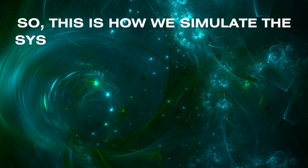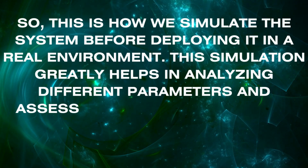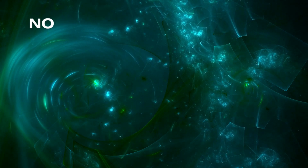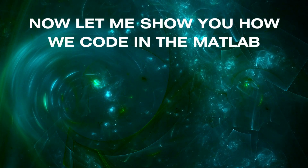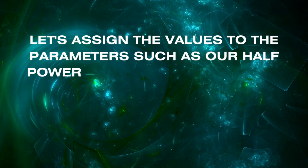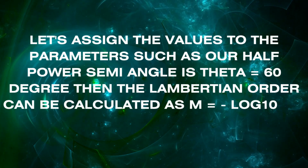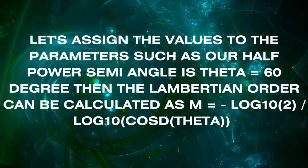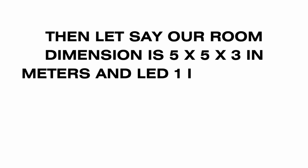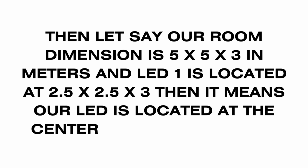So this is how we simulate the system before deploying it in a real environment. This simulation greatly helps in analyzing different parameters and assessing the performance of the system before it is actually installed in the room. Now let me show you how we code in MATLAB. Let's assign the values to the parameters, such as our half-power semi-angle theta equals 60 degrees. Then the Lambertian order can be calculated as m equals log10(2) / log10(cos(theta)). Then let's say our room dimension is 5 by 5 by 3 in meters and LED 1 is located at 2.5 by 2.5 by 3. Then it means our LED is located at the center of the room, right?